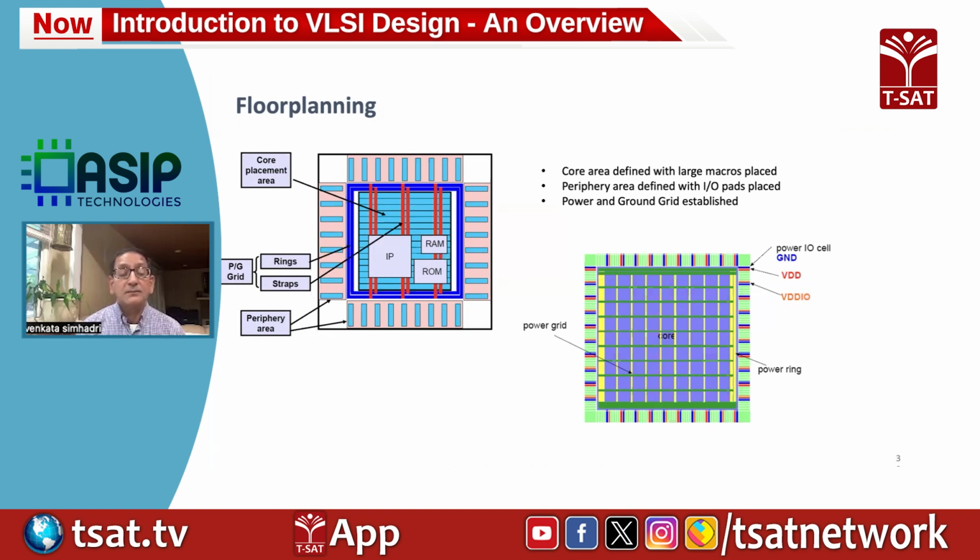Similarly here, you take all your key blocks, and based on how they are connected and how the data flows, you decide where these blocks are placed in the design. And then you define your IO ring, where the inputs to the chip are coming from, where the outputs are going. And then also, the most important thing, the chip needs power and ground supplies, and you have to decide where these power and ground inputs are placed in the chip.